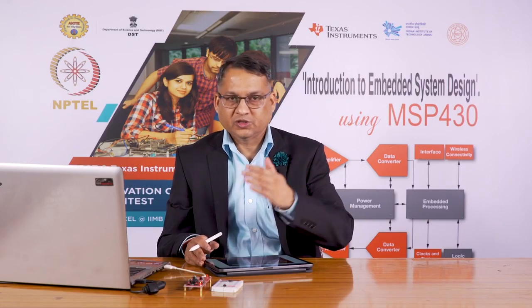A switch is a mechanical device. It consists of two metal plates with a shorting cover over it, which, when the user presses the plastic button, the metal cover inside shorts the two contacts of the switch. When the user releases it, the cover retracts and the connection is broken. So, using this arrangement, the contacts of the switch move between two states: switch is open or switch is closed. To ensure that the switch retracts, there is usually a spring arrangement.